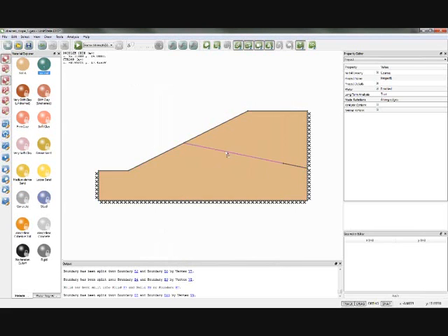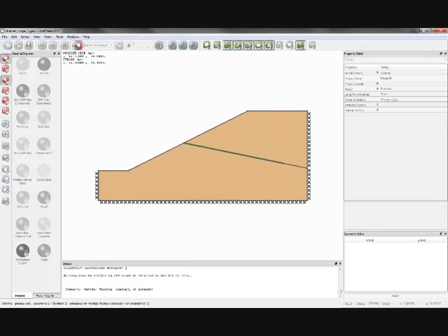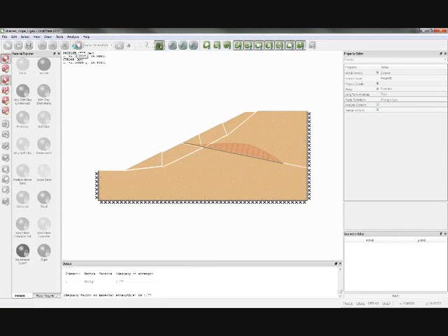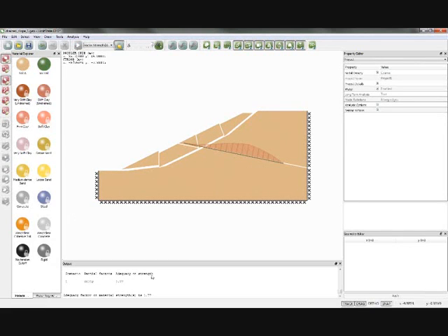So effectively we've now got a soil nail in the problem, and what that should do is add a bit of strength to the system and increase the stability. In this particular mode, modelling a soil nail, the failure mechanism can pass through it, and what we've got is a factor of safety on strength of 1.77, so it's gone up from 1.63, so it's had a reasonable effect. This graph that's appeared here shows the plot of the tensile force in the nail due to that mechanism.